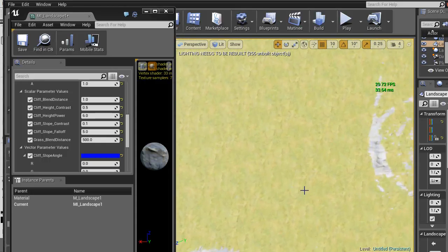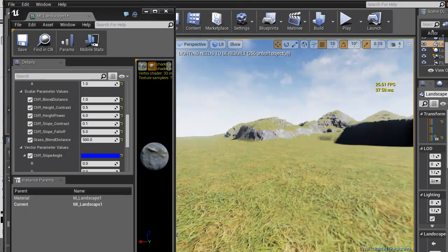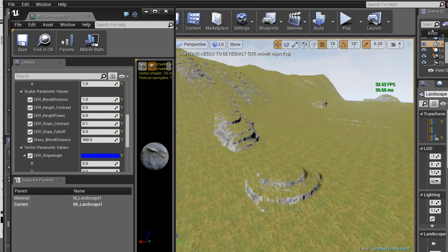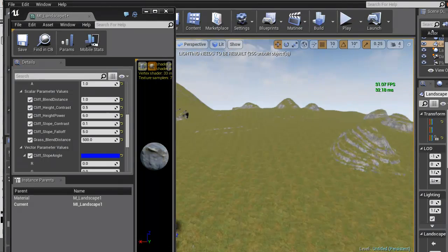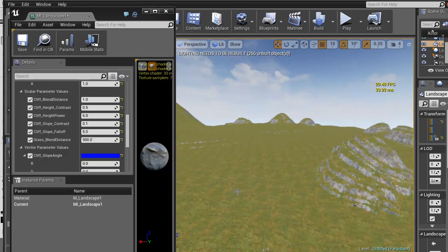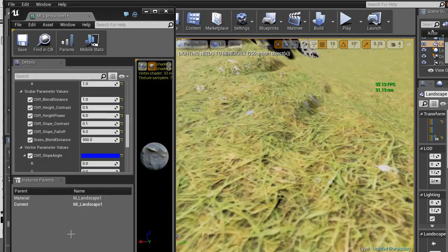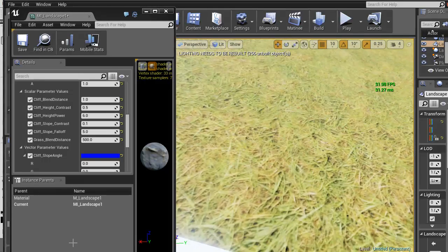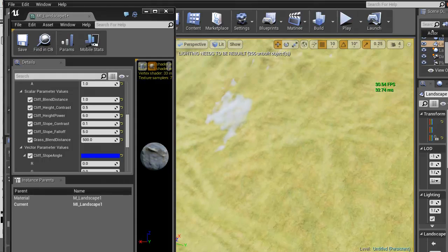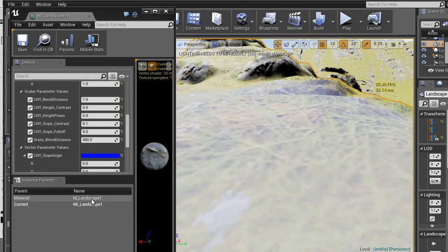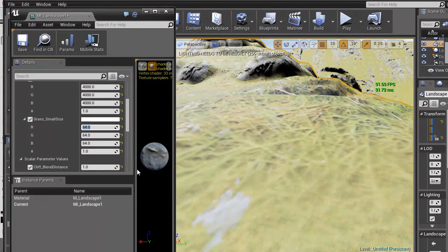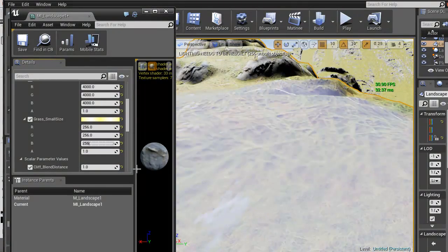And you could, if you wanted to, also multiply that whole thing by a complete total diffuse tone color, so that you have large patches of brown and large patches of green, and then as you move in, your resolution gets better and better and better. I mean, you figure the character's height's probably about right here, so that blend distance is too close, and that size is too small. But I'm just illustrating that you have that ability to tune it however you really want.